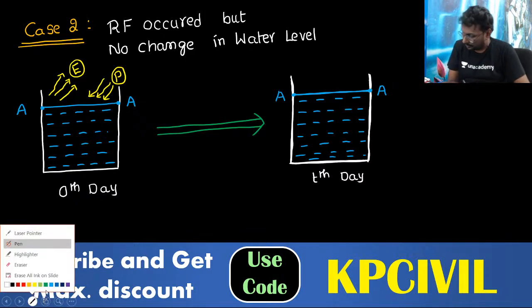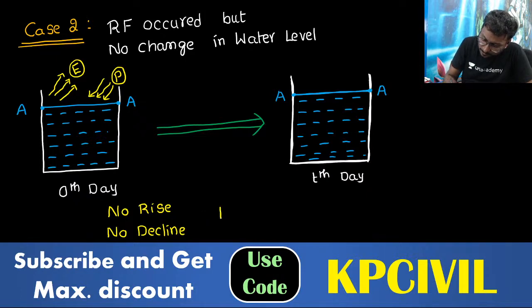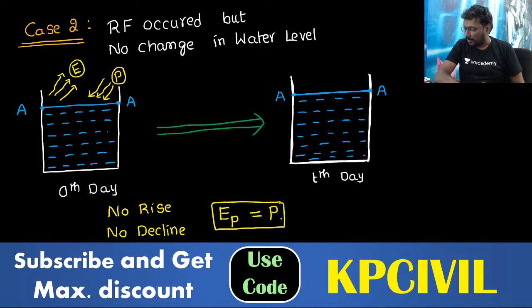Because, very good Ramakrishna, nice to hear. No rise of water and no decline of water, because whatever evaporation occurred from the pond is equal to precipitation. Very good Asif. Very good Ramakrishna. Pond evaporation is equal to P. So we take the precipitation value from the nearby rain gauge station. Clear? Directly we'll measure the precipitation value from the nearby rain gauge station. So pond evaporation is equal to precipitation.